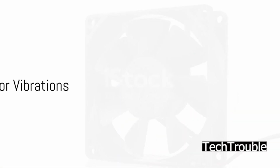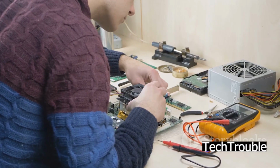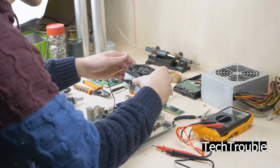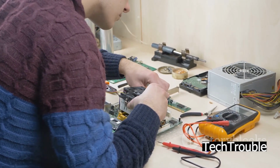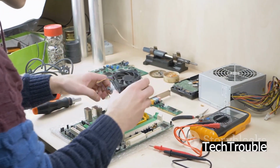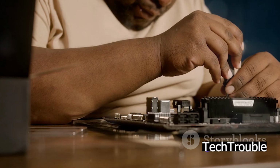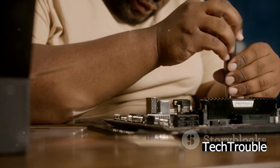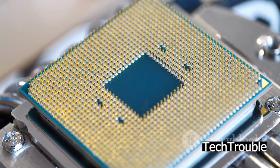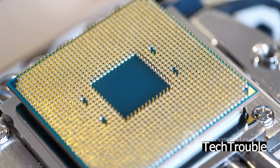Last but not least, noise or vibrations. Excessive noise or vibrations from the CPU cooler or fans can indicate mechanical issues or improper installation. To resolve this, ensure all screws and mounting brackets are securely fastened and that the CPU cooler is properly seated on the CPU. Adjust fan speeds or install quieter fans if noise levels are bothersome. Monitor temperatures and fan speeds using software utilities to ensure the CPU is adequately cooled without excessive noise.